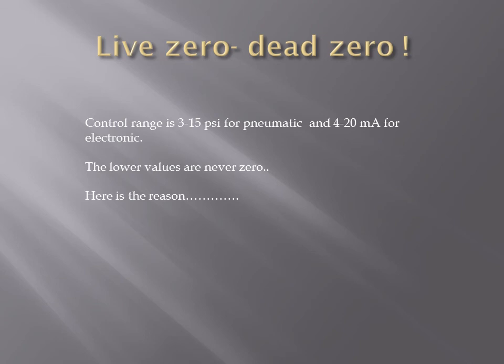This is because of the concept called live zero, dead zero. It's very simple. Assume that an instrument has gone faulty. In that case, it will never generate an output to the controller or the control valve, so the output will be 0.